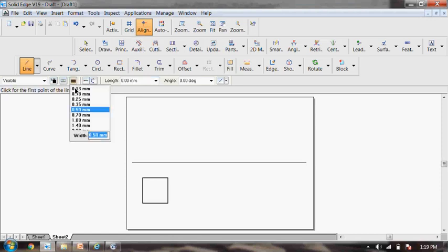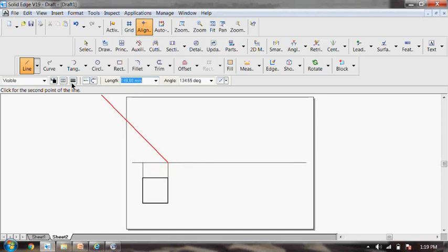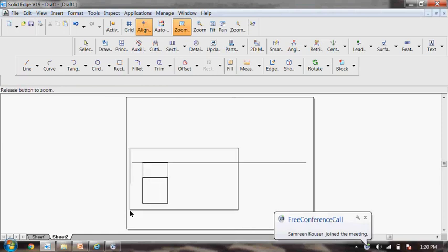Then after that, decrease the thickness, draw the projection line, a 90 degree line to get the front view. Increase the thickness to 0.5 and then join it. So this is the front view and top view of the lamina. Use the text command, label them with A, B, C, D, A dash, B dash, C dash, and D dash as usual. Label the XY line and mention it as VP by HP as I have shown in the previous problem. Then after that, HP angle, the lamina is inclined at 30 degree to HP. So the next step, I'll just zoom this part and I'll explain.